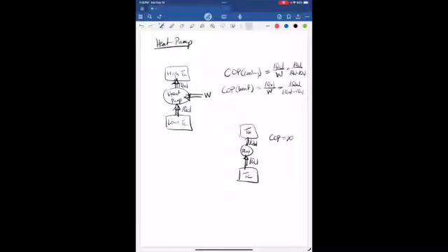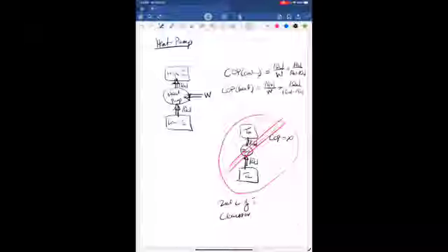And so Clausius realized this was impossible. And so he stated the second law of thermodynamics as exactly that. So this is also the second law of thermodynamics. This is the Clausius form, after the person who discovered it, Clausius. And it states that it is impossible to pump heat from a low temperature reservoir to a high temperature reservoir without the input of work.